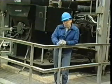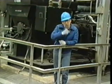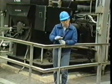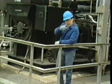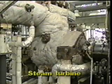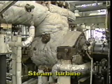In higher speed and load applications, the steam or gas turbine is the most commonly used. Now, in low-speed or small-load compressors, electric motors are sometimes used. Let's take a closer look at these different drivers. In steam or combustion gas turbines, speed-increasing gears are often needed between the turbines and the compressor shaft and are connected with couplings.